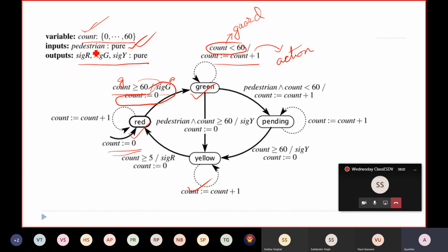Let's say, what can be the cases when you are thinking of a traffic light controller? One case may be that there is no pedestrian. Another case may be that some pedestrian has pushed the button and is waiting until you have got the pedestrian input. That means the pedestrian is requesting that you now set the light to green so they can pass. And the third case can be that the pedestrian is now crossing. That means you have already received the pedestrian input from the push button.